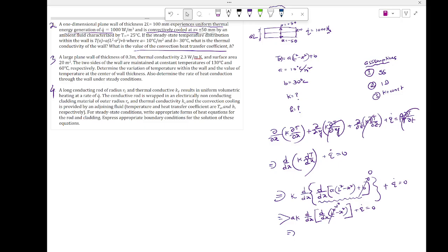You see, Chelsea pointed out a very important thing. The temperature equation was given, right? So to find the conduction, you need the temperature. You use that temperature distribution equation to find the two temperatures. You understand? Or you can use this dT/dx to find that value. Can you do that? At the surface at x equal to 50, you're gonna find the conduction. Okay, Matt, that part is important. Please focus on that.